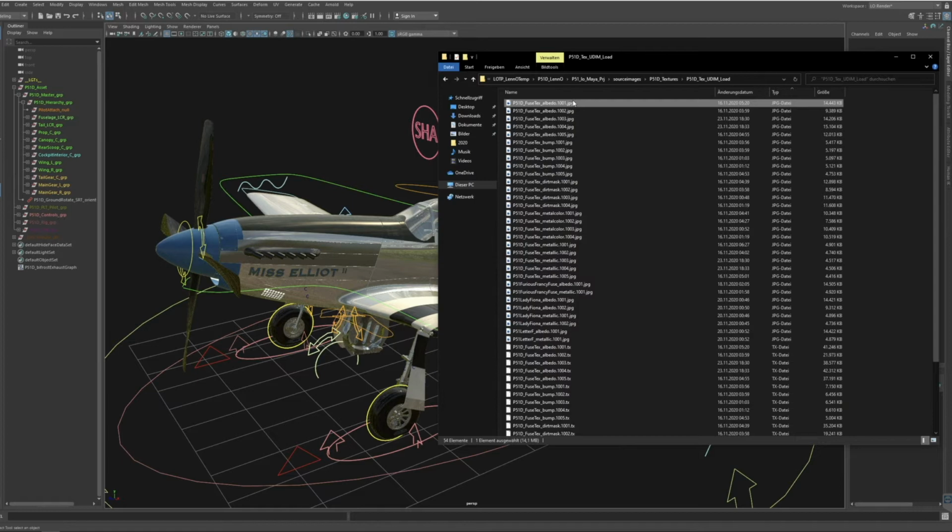I think for pretty much everything I've rendered for the last, whatever, 10 years, 12 years, maybe even more, I can't really remember, I don't even remember how old OpenEXR is now. But for the majority of doing CG, I've never again rendered anything into any other format than EXR, because in the end, you can work super comfortably with them in Nuke, and there's really just no reason to render out in any other format. So use OpenEXR, and you may use OpenEXR as a texture input.